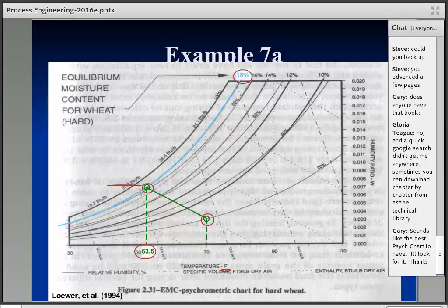Now there is a problem here that it's an iterative process. You have to know this temperature to know where to look it up in ASA data. You have to know the T sub G value. But if you look at this process, you can estimate on almost any drying problem roughly where you're going to end up.